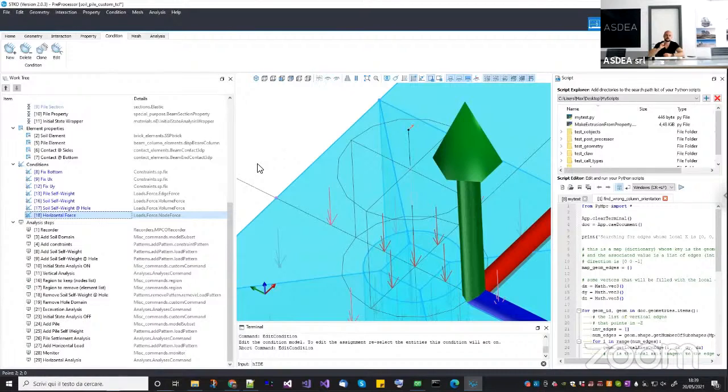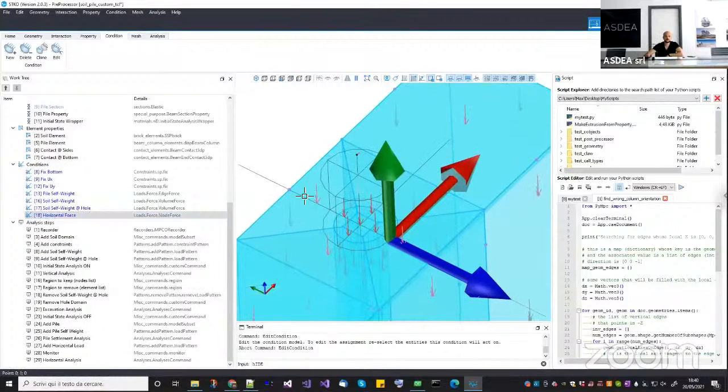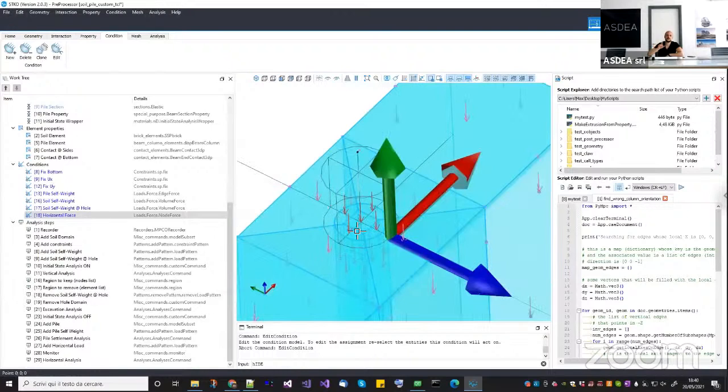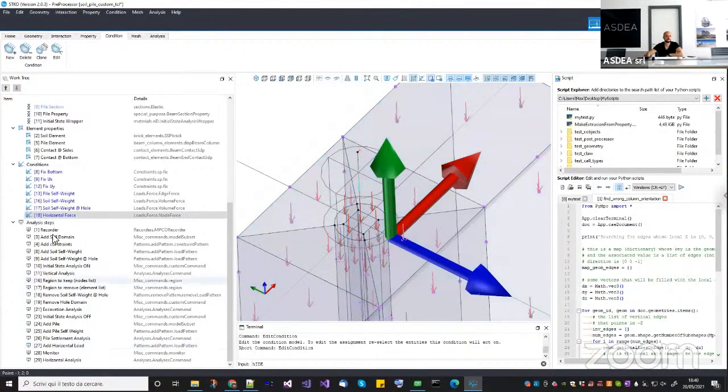The problem is that whenever you try to write to a memory space that has been removed, you cannot predict what the result will be. It can make a crash or it can simply create random results. So this was the reason why you had crashes. Now all the steps that we need to perform are summarized here: a gravity load of the soil, excavation of the hole, putting in the pile, then doing the settlement of the pile, and then applying the horizontal displacement.